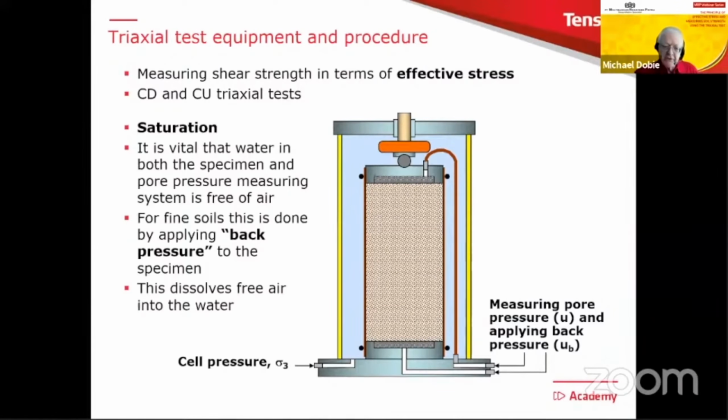So the saturation stage, this one is really important. We're only going to get good data from this testing if the entire system is saturated, which includes the sample itself. If you've got air inside it, then you're not going to get the right results. So we need to saturate the sample. And if you simply put it in contact with free water, you're not going to get rid of the air.